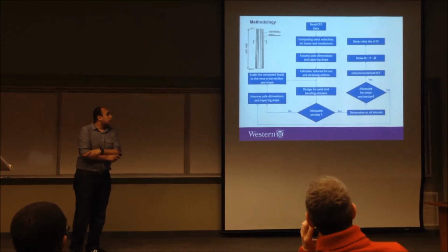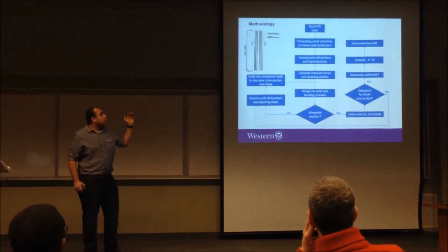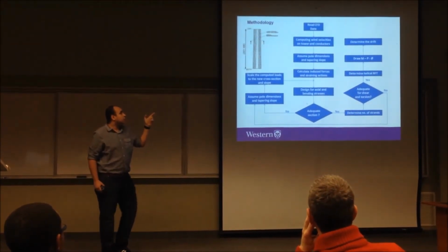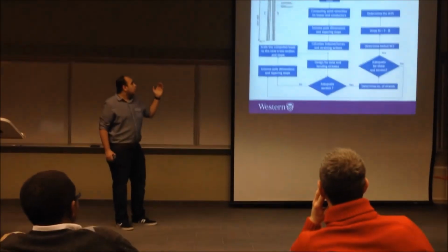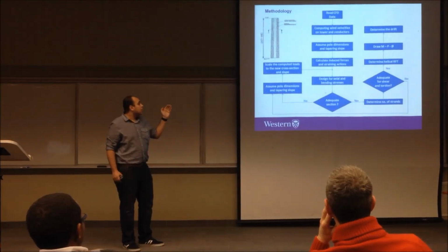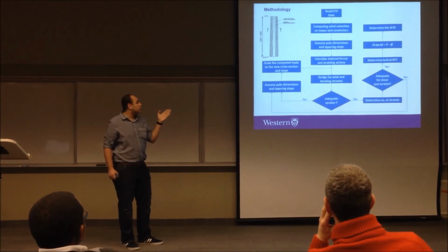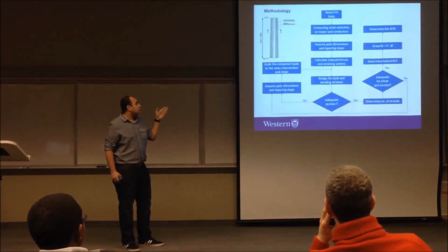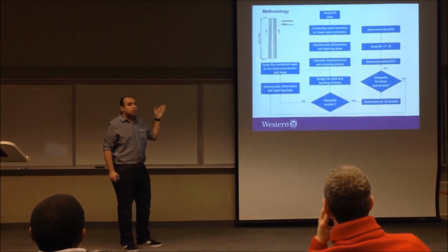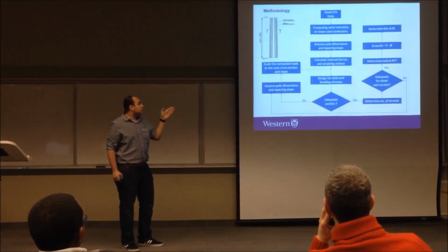So we now have computational fluid dynamics data. We can compute wind velocities on the tower and conductors, then assume pole dimensions and tapering slope, then calculate the induced forces and straining actions on such poles and conductors, design for axial and bending stresses, and check if the section is adequate or not. If it's not adequate, we assume new pole dimensions and tapering slope, scale the computed loads according to the new cross-sectional slope, then design for axial and bending stresses.